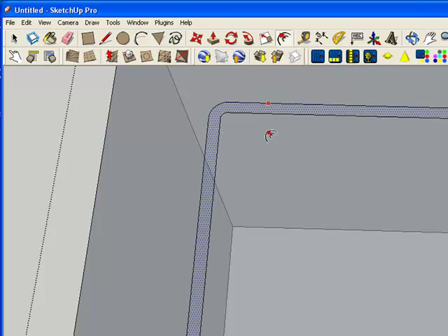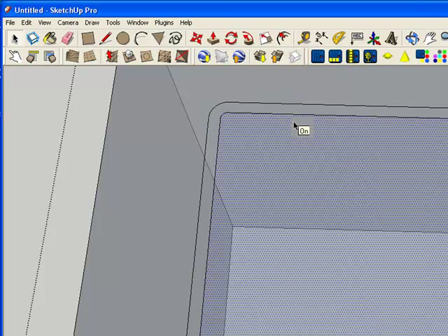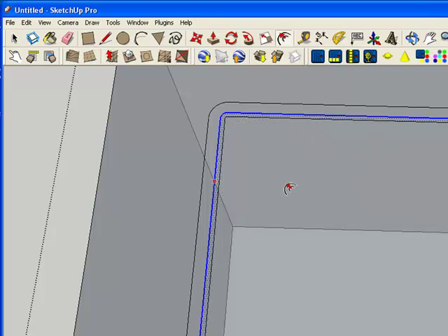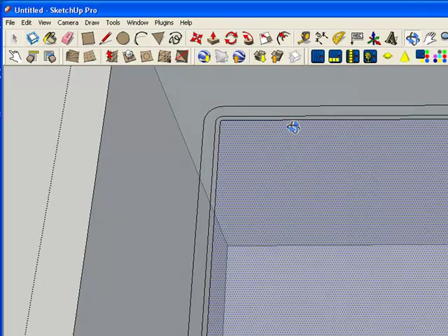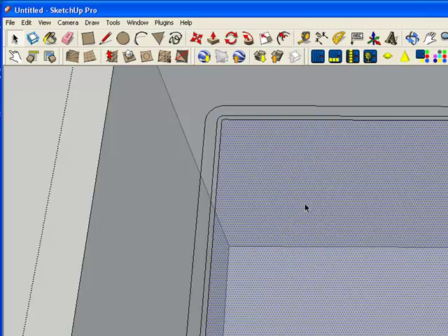It's not straight up and down. So I'm going to click this and collect this inner one, use this tool again, and come in with another section, all right, that will represent the bottom of the sink that is slightly smaller than the top of the sink.